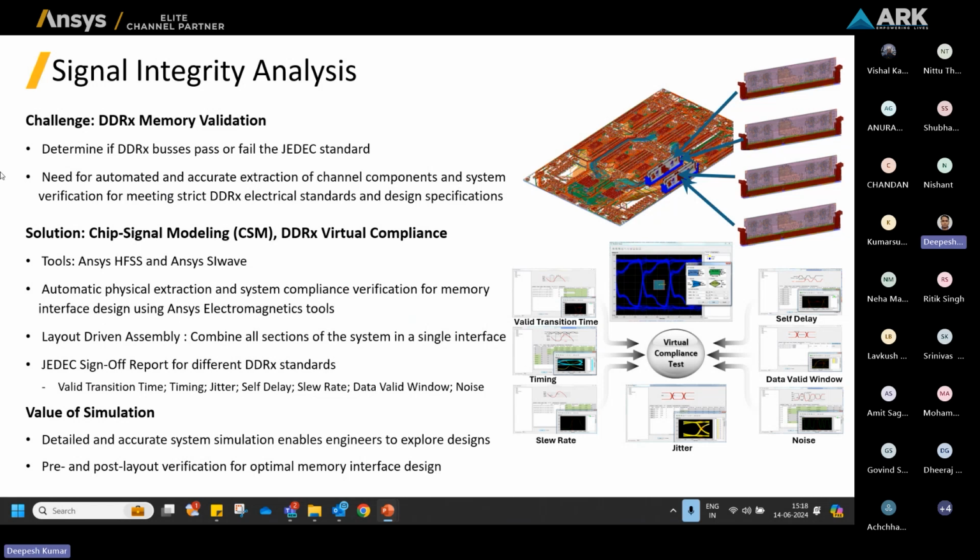You can analyze DDR6, and DDR6 plus is also coming in newer versions. You can generate a JEDEC sign-off report, which has valid timing, jitter, cell delay, slew rate, data valid window, noise, all in a single go. You only need to bring the PCB with your components and your DDR, define the channel, and then analyze it with time domain analysis. You can also see the frequency domain as well.